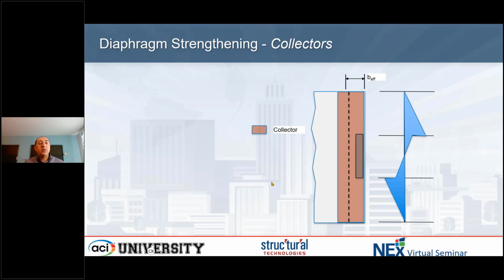Again, when we do analysis, we determine the amount of the steel collector and we design it for new construction. But if I'm dealing with an existing structure, I do not have that, then I need to calculate the required collector or tension reinforcement, how much I do have in place, what is that delta, the difference, and try to mimic that with FRP.